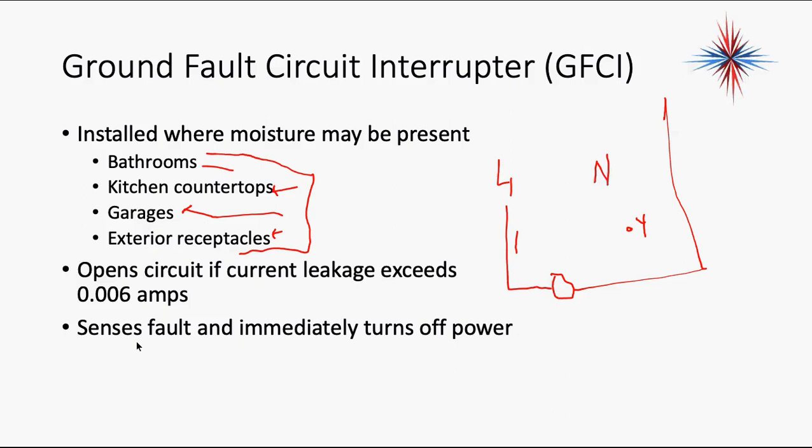Now, basements will have GFCI circuit breakers. So a lot of times condensate pumps, you know, the pumps that actually hang on the side of an air conditioning system or a furnace and pump the water out. Condensation gets pumped out someplace. A lot of times condensate pumps are plugged into a GFCI outlet.